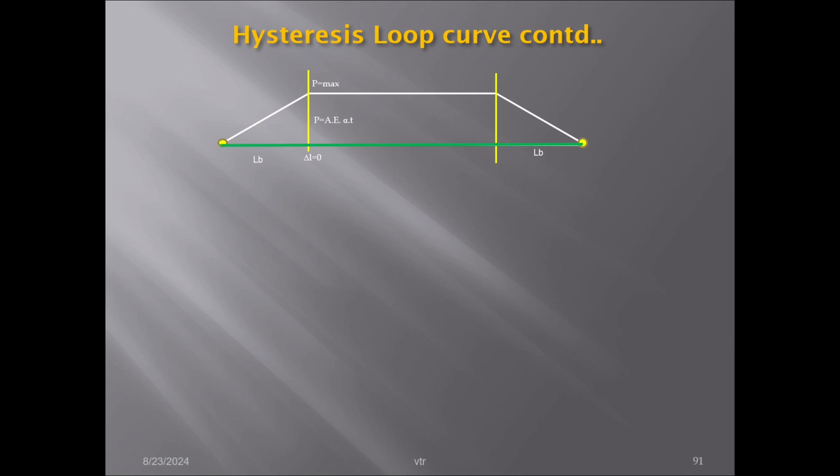What we used to do is record the existing gaps and compare them with the theoretical range of gaps prescribed. We have seen various tables available, where we can find the range of gaps for different temperatures, for the various zones and various rail sections. With that we are able to check and confirm whether our LWR is working properly or not. How the theoretical range of gaps has been framed in the tables is what we are going to discuss now. That is all based on the loop curve only.